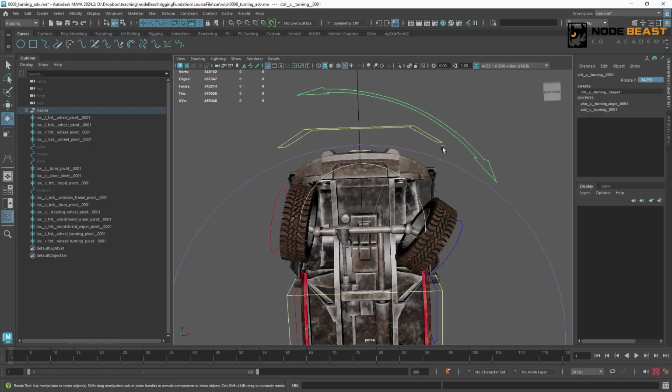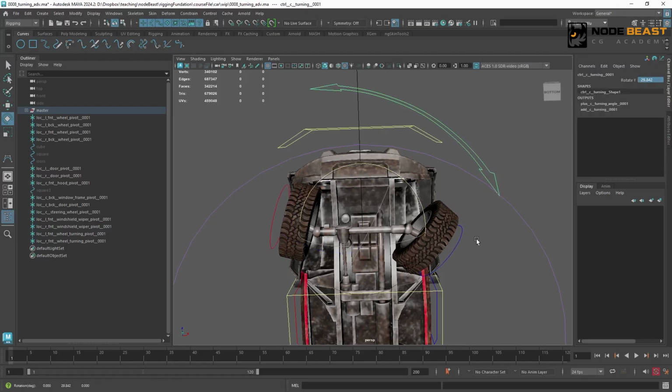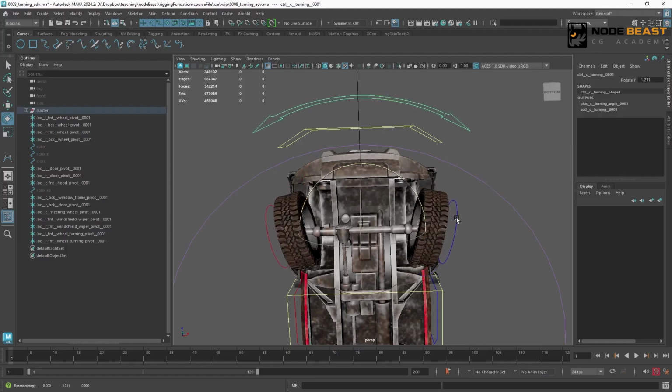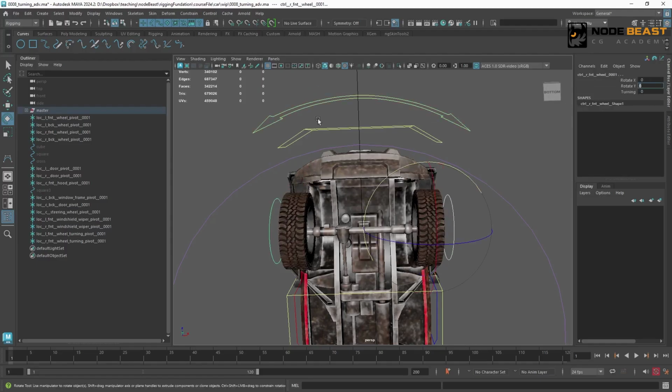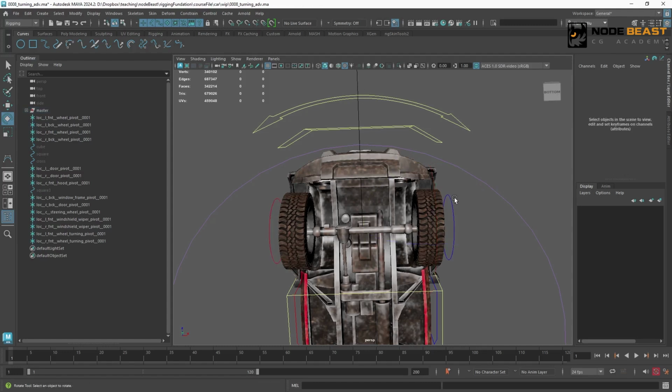For example, if we're at 30 degrees now, it might be a result like this. The inner wheel might be, say, 1.2 times the actual rotation angle. And this side is, say, a 0.85 multiplier. But when we are closer to the center, these two wheels compared to the actual rotation angle won't differ by that much. It's closer to a one-to-one effect.